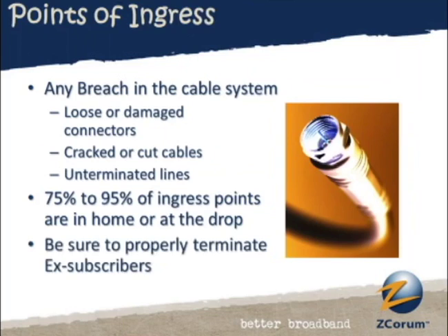And this is something interesting that operators might not think about: you've got to properly terminate an ex-subscriber. If you disconnect somebody and then that's not properly terminated, that can be a source of noise. Yeah, absolutely. I mean, if you don't actually disconnect that drop from the tap or make sure that it's completely trapped out, you're still completely vulnerable to all of that noise that's coming in.